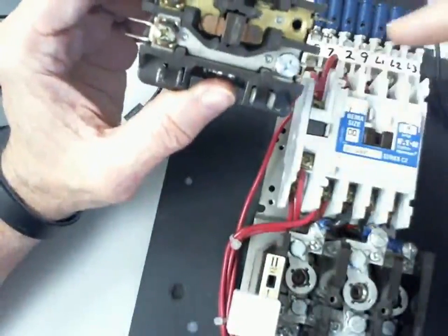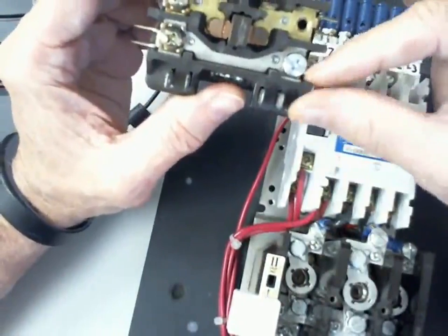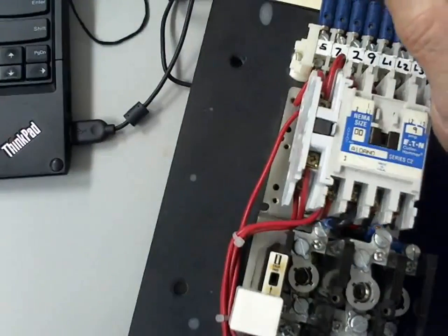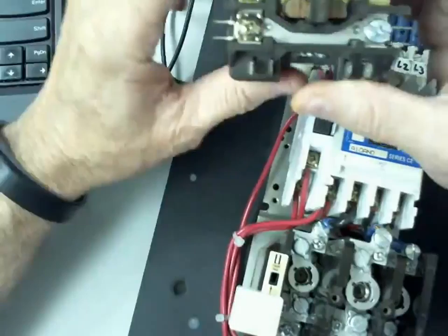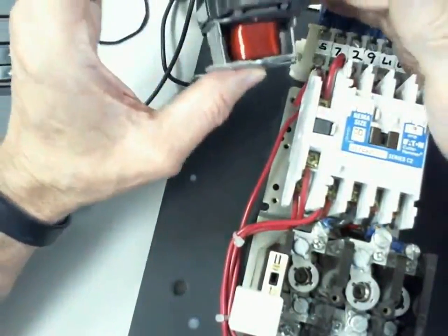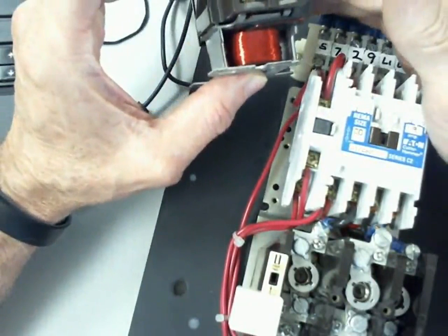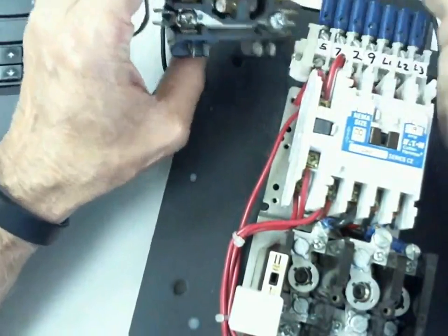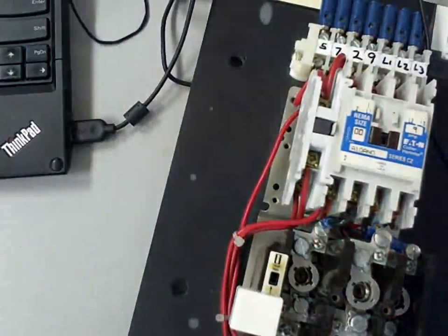So that means this side, and it's 240. So that means you got 120 volts to ground on the 240 side. If you get between any 240 and ground, that's 120 volts. So be careful when you work on these. This is the compressor relay contactor for an HVAC system. So be careful when you work on those with power on. Of course, you need to guard these poles too, right?